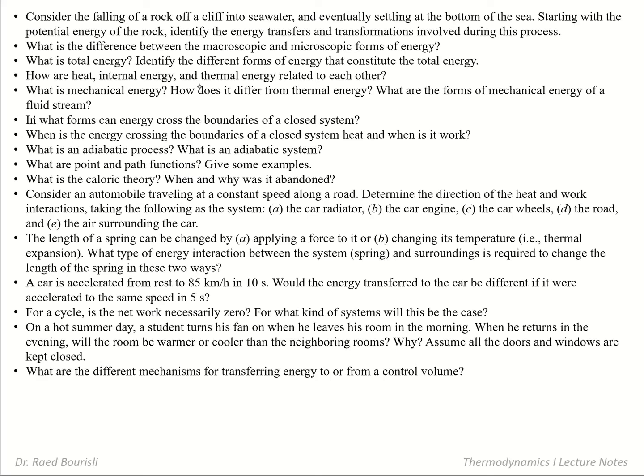Consider an automobile traveling at a constant speed along the road. Determine the direction of heat and work interaction, taking the following systems, first the car radiator. Of course, there's no work in the radiator, just flows: water flows in, and there's a fan that cools it. There is maybe some boundary work, some flow work coming in, but mainly it's heat that's transferred between this fluid and the surrounding air.